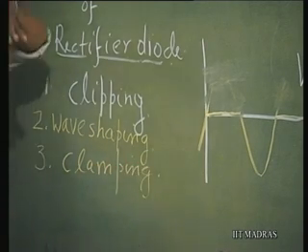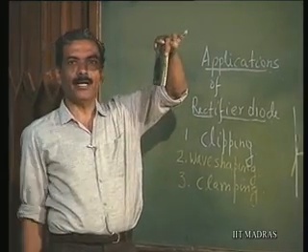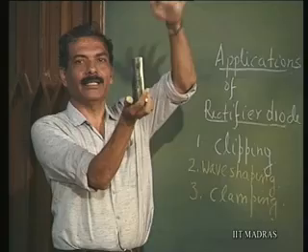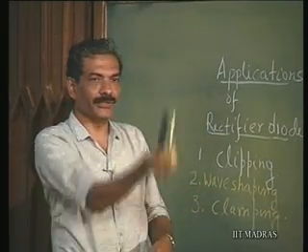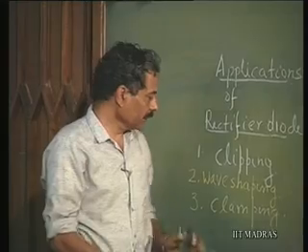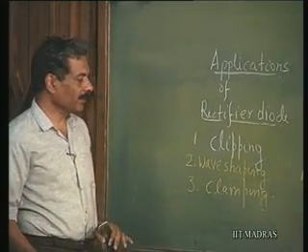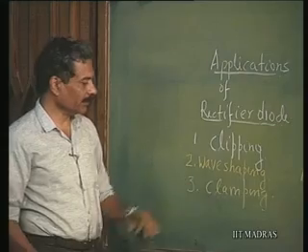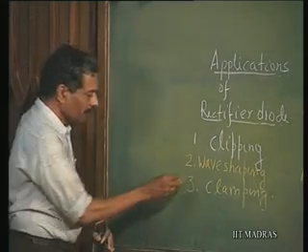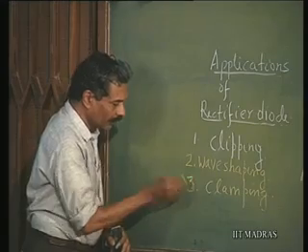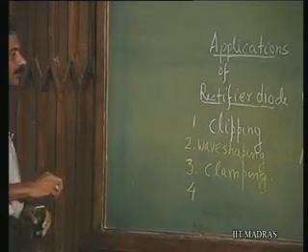That is letting the waveform, whatever it is, sine wave or triangular wave, get clamped at the top or clamped at the bottom, so that it can be clamped to any level of voltage or current, right. So, this is what is meant by clamping. We will again see this detailed discussion about this later, what is meant by clamping. So, clamping is another operation as far as this is concerned.